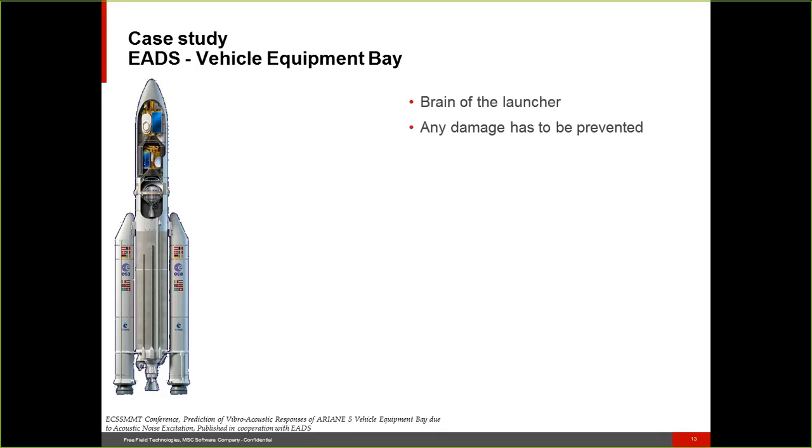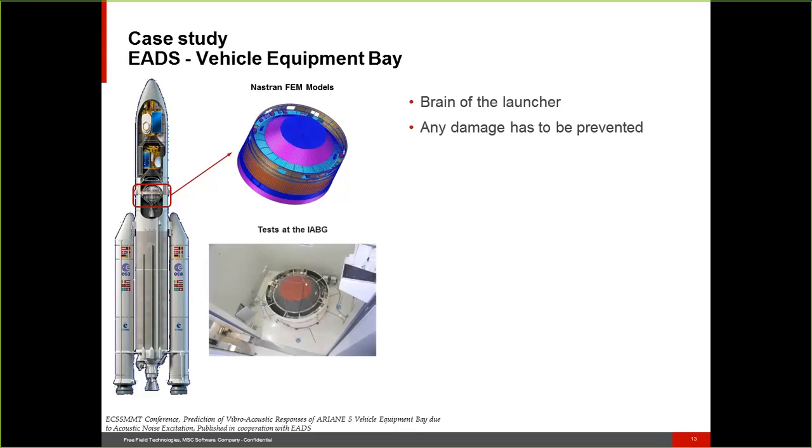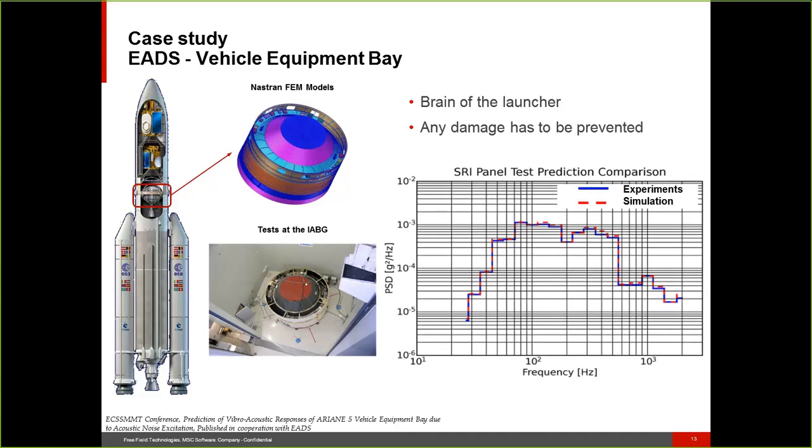The equipment bay is the brain of the launcher, and any damage needs to be prevented. A finite element model of the equipment bay structure has been built and submitted to a diffuse sound field. Numerical results were compared with experimental ones, showing excellent correlation over the complete frequency range of interest.